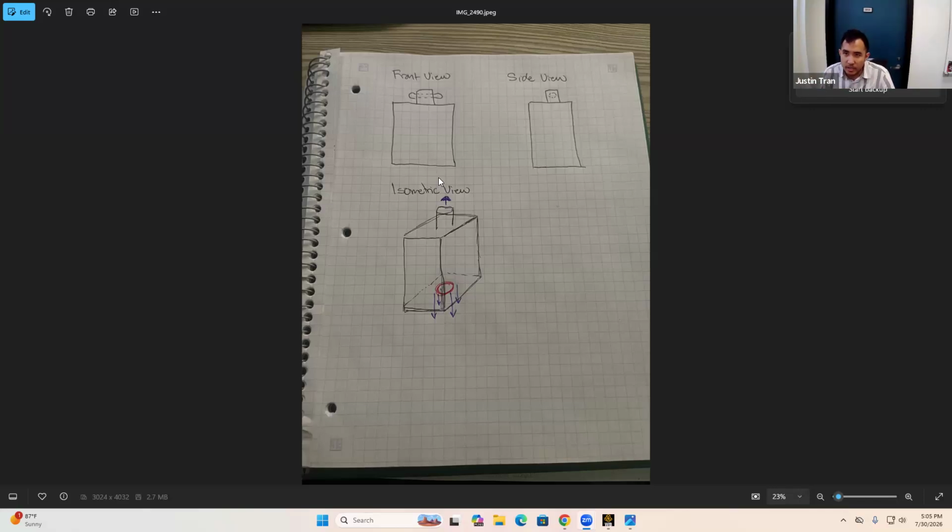You do have this part up here with a lip. Whenever I see something like that, you can think of a torsional load, a load that's twisting up there, and see how that torsion propagates through the structure. Torsion induces shear stresses in the model, and you may get some shear failure. For a part like this, tension and compression probably won't cause that much stress; you'd have to apply a lot of tension to get a good amount of stress. But with torsion, you get a lot of shear stress, which will fail faster than tension or compression.